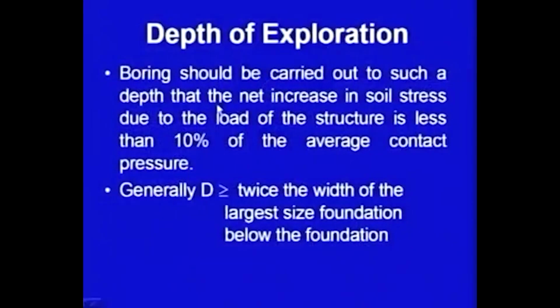As a rule, the boring should be carried out to such a depth that the net increase in soil stress due to the load of the structure is less than 10% of the average contact pressure. This statement we use as a thumb rule. What it means is that there is, let us say, some contact pressure, and as you go deeper and deeper, the incremental pressure, the increase in pressure because of the foundation, goes on decreasing.